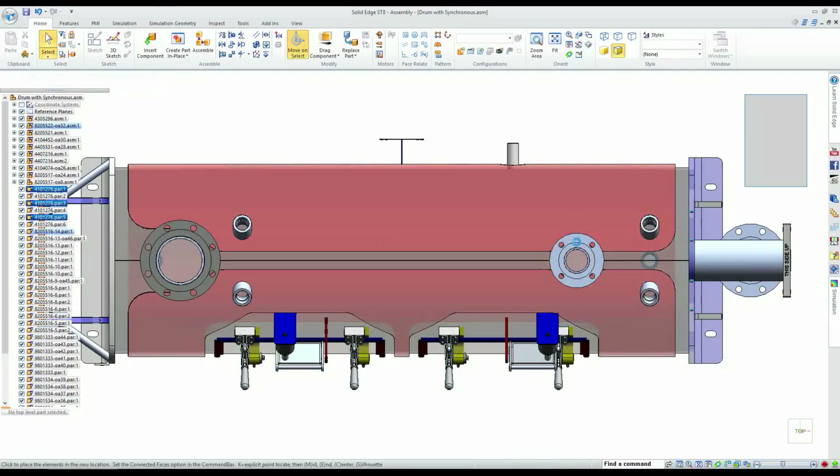We're just now learning that we can bring in our SolidWorks files or any other dumb solid from any other CAD system, manipulate it, recognize some of the features within it, and turn a dumb solid into a more intelligent solid that can be easily adjusted and modified to the new design that we need for our machines.